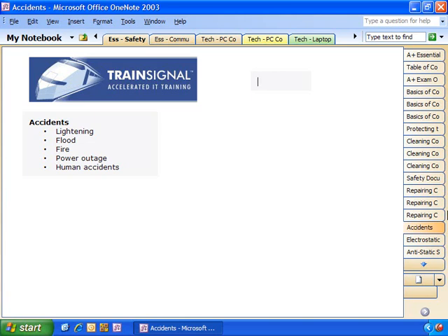So just some examples of what to do if you have a fire and to try to prevent fires caused by, say, over utilized electrical circuits. You need to monitor how many amps your electronics equipment is pulling, and don't overutilize electrical circuits. What I mean by that is people who hook up one power strip to another power strip to another power strip and have 50 amps being pulled off of a 15 amp electrical circuit. If the breaker doesn't pop, that can cause a fire eventually.